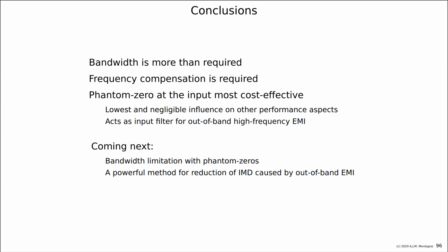And if my controller also has an infinite input impedance, the op-amp, then the feedback network and the source impedance also don't introduce attenuations in the loop. So a unity gain feedback voltage amplifier is very difficult to compensate with the phantom zero, with an op-amp, because there's no attenuation in the loop.